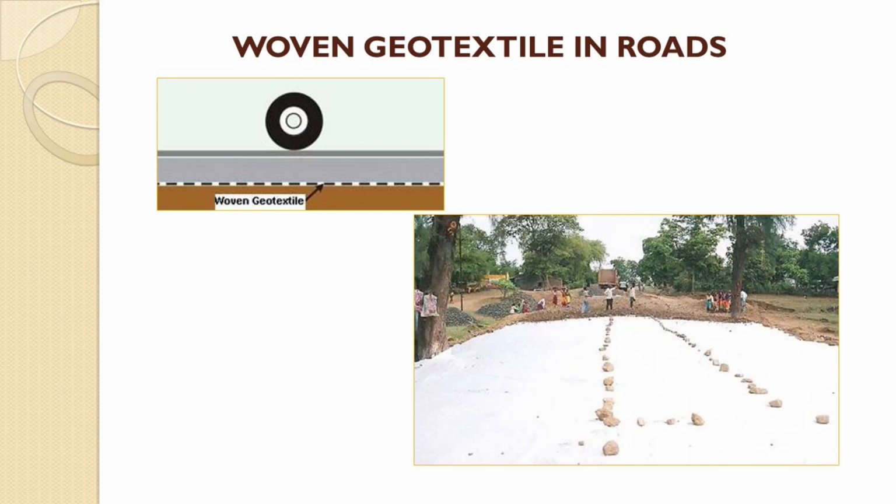And this is the example for asphaltic reinforcement. There are certain procedures. The existing road is milled, graded, then you put a tack coat, lay the grid and material over it, then move directly over it. And the paving which you do, originally they started in the research with 100 mm.